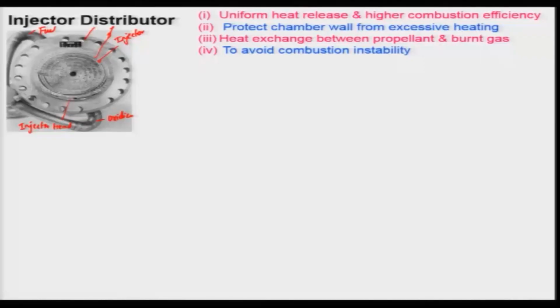And also the intense combustion will take place inside the combustion chamber, away from the wall. So, these 2 things have to be looked at, and also the homogeneous mixture must be avoided, and combustion should not take place near the injector head.